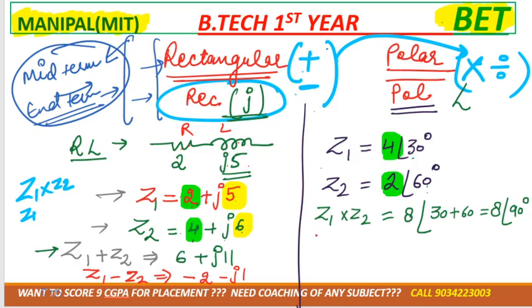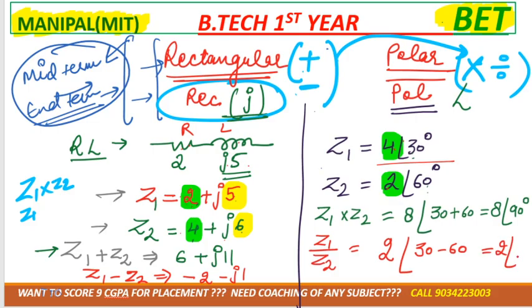Okay, again if we want to divide, Z1 divided by Z2 is how much? 4 divided by 2, the real term is divided by the real term, 4 divided by 2 is 2 only, and the angle would be subtracted. So how much will the angle be? The 60 goes at the top, so that would be 30 minus 60, so the answer is 2 angle minus 30 degrees.